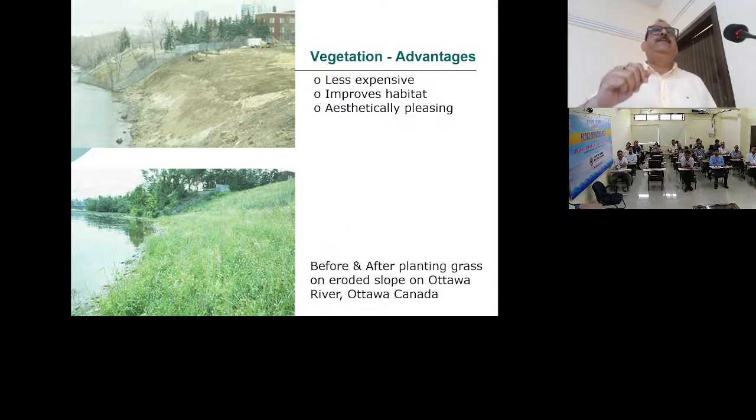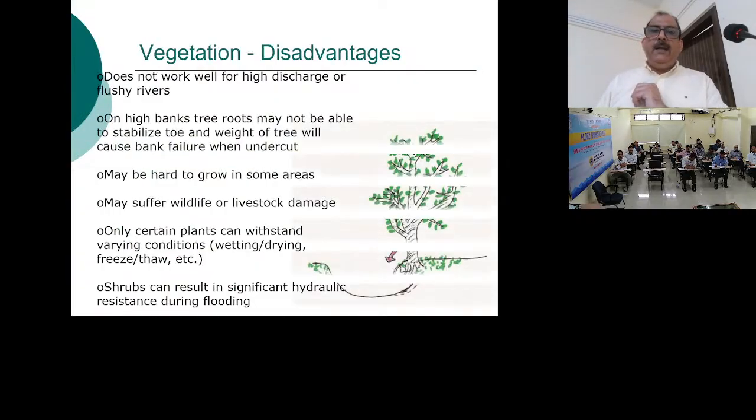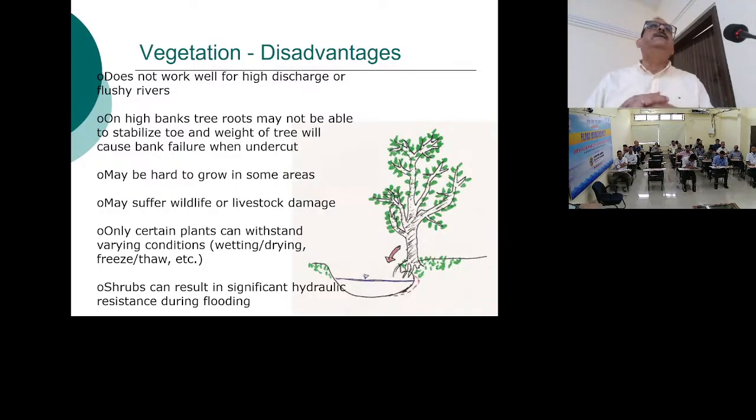But take Majuli Island, again in Brahmaputra. You see that bank slope is very flat, almost flat. If you go inside, they are called Jaubon. It's a special tree that arrests silt. That is effective there. But when the bank is vertical, scouring is occurring at a very low level, this is not effective. Again, it has many other issues. It increases your flow resistance, that Manning's N value, I think you know. That N value is increased by these vegetative measures. And then there is a possibility of damage by livestock.